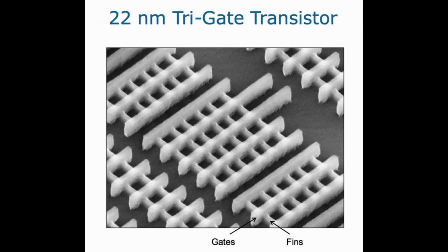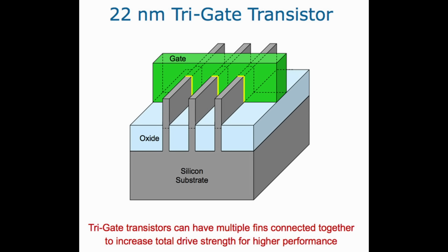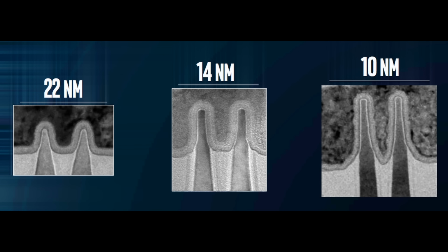Remember the reverse engineered Intel 386 from Ken Shirriff's blog? While it was a CMOS design, it was long before the invention of FinFETs, so it used planar transistors. Today, standard cells are based on FinFET transistors. And FinFET transistors don't just have a single fin, they usually come in flavors of between 2 and 4 fins per transistor. The reason for that is performance, drive strength, and reliability. As you saw before, early FinFET nodes didn't have very pronounced fins. Multiple fins were needed to achieve the required transistor performance. That's why FinFETs use multiple fins.